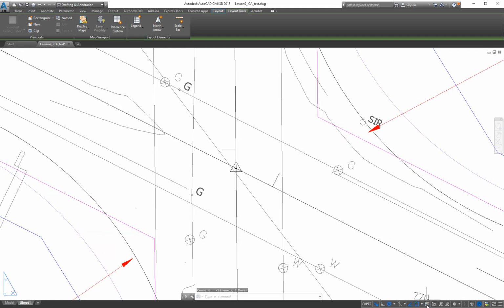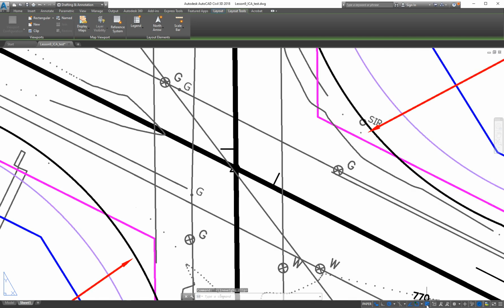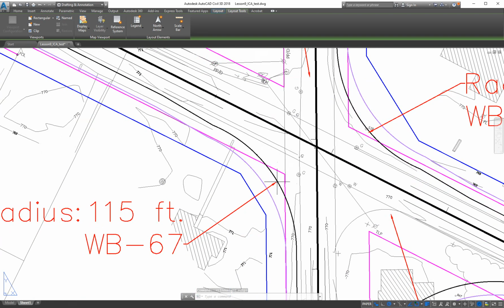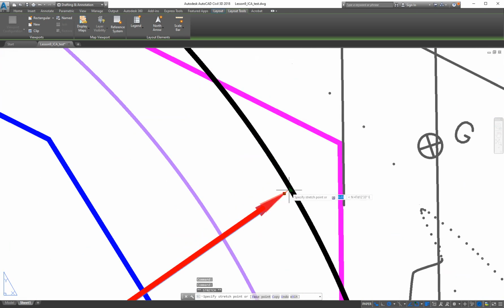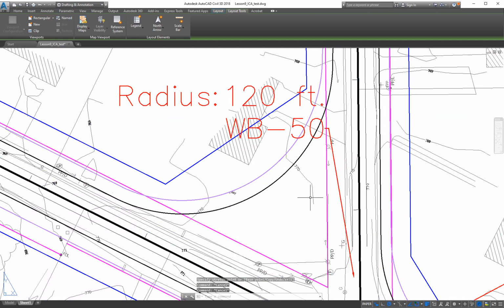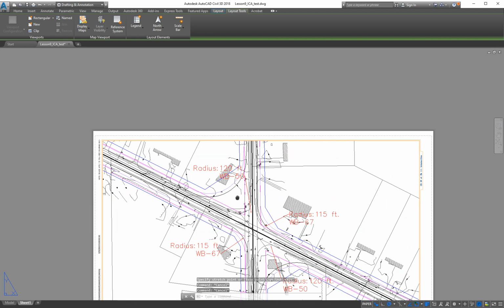Okay, now everything is set to the minimum thickness. You can see it, but that's not its true plot thickness. All right, so I'll turn that back on. I'm turning it on now because that shows this edge of pavement really well for me. And I want to snap this arrow until it's right on that line. How's that, right? So we had to move these callouts, escape, to bounce back, all right, because I'm at 1